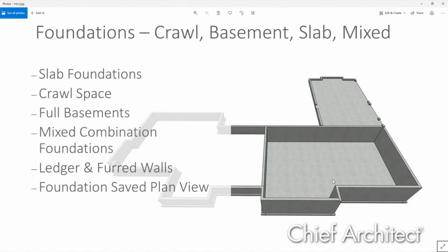So what I ended up doing was starting with a garage and then dropping that down, say 3.5 inches, and renaming it to be a porch. But sometimes it gives me difficulties with the slab. It kind of makes it a pool or a tub situation, because the walls from the foundation kind of rise up. So I have to go back and forth playing and tweaking.